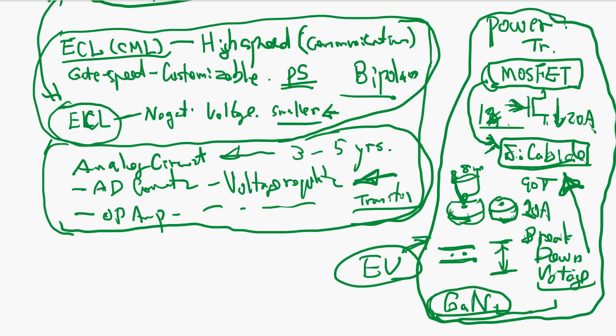Okay. Now MOSFET is the cheapest one, but MOSFET has a little bit of a problem on rise time. When you switch off, rise time is slow, and the power consumption efficiency is not that great. That's why silicon carbide is preferred. It's a more expensive chip, but silicon carbide is used in most EVs, and the new one they try to use is gallium nitride. So this is a different field.